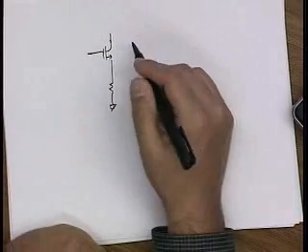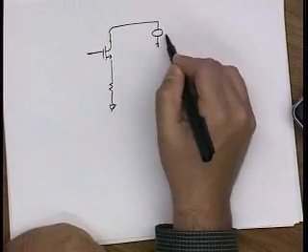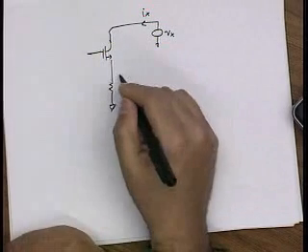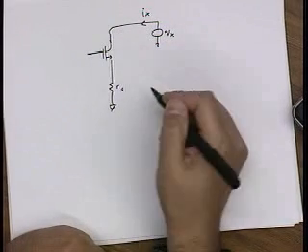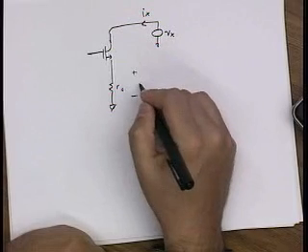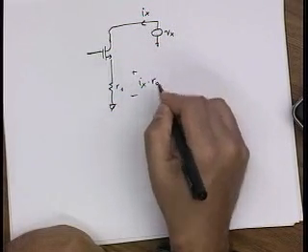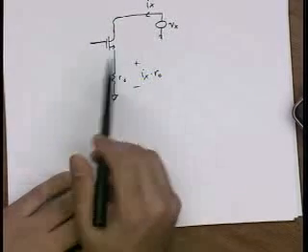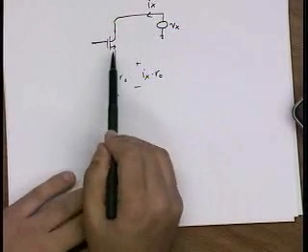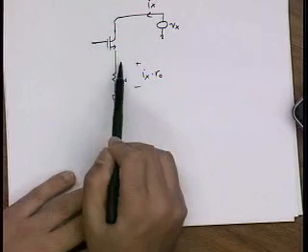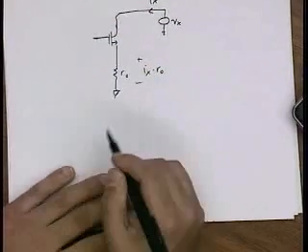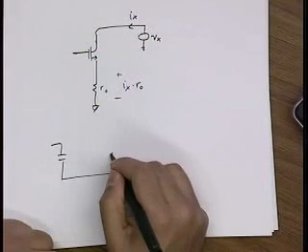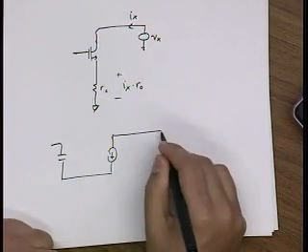So in a cascode device, if I put a test source here that sends in a test current, that test current flowing across here produces a voltage Ix times Ro, right? And that produces negative feedback on this transistor, right? So this actually excites the transistor. Let's just do a quick calculation for how this works.